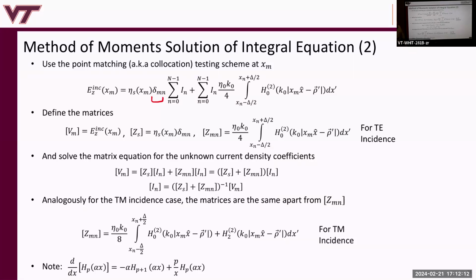So what will be the coefficients? The basis functions have some coefficients when we expand in the basis. The current coefficients are still here, in both terms. This is the total field, the sheet impedance times J, and this is the scattered field term. They're in both terms, but the current is weighted by the sheet impedance. At this point, you assume you know the sheet impedances, or else you can't solve this. But I'll show you how to solve it without knowing those at first.